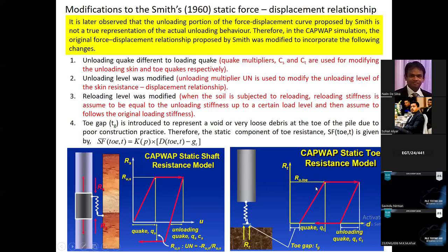Similarly, the toe response is also modified. They have introduced a toe gap to represent any soft toe condition, right? So this is the toe gap and the toe response. This is the unloading response. So the quakes are different, right? This is the current model. Actually, the current actual model is something like this.